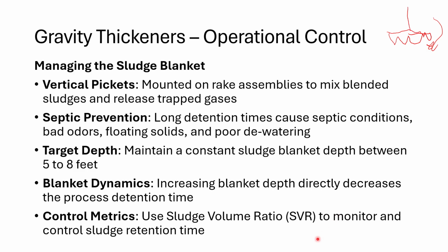Okay. Here's something you do want to know, particularly if you're going for a level 3 or level 4 operator exam. There's this thing called a sludge volume ratio. There's also this thing called a sludge volume index. I will refer you to the Ragsdale chapter on mathematics for wastewater operation to look at how that's calculated. But the idea here is we're continually taking readings in our process, and we're going to use those readings, whether it be from a sludge judge or what have you.